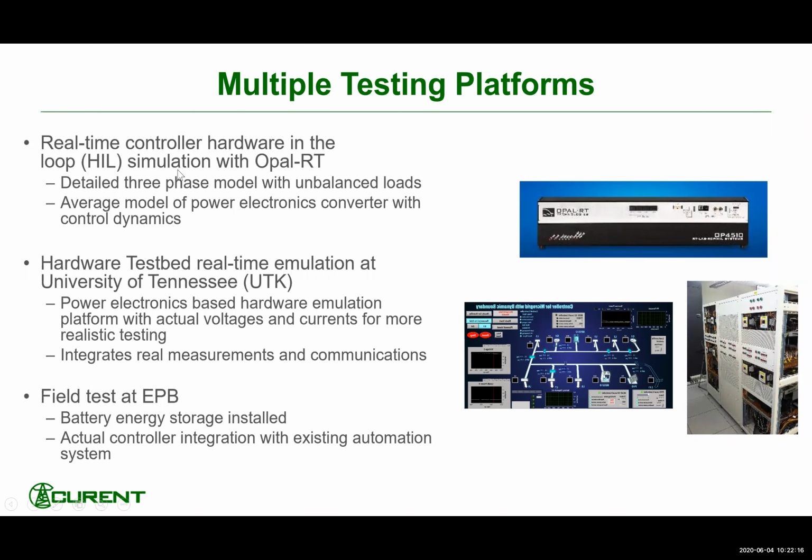Step 1 is the controller hardware-in-the-loop testing. That's to say, the grid or microgrid assets and communication are emulated on the hardware, I mean the real-time simulator, but the controller is the real thing, external to the real-time simulator. In this way, we can do the controller hardware-in-the-loop testing to verify the controller performance.